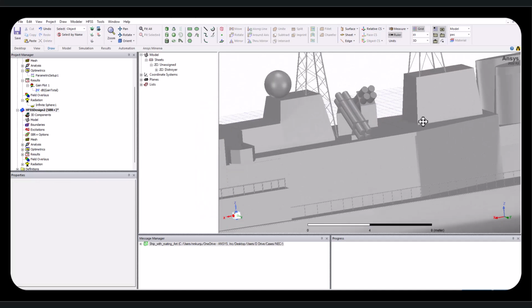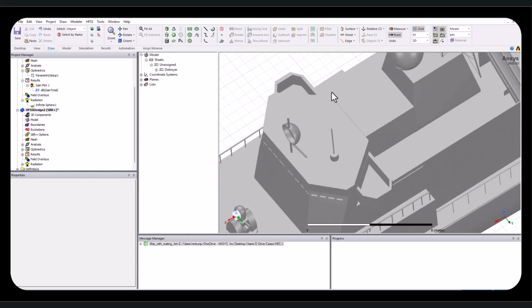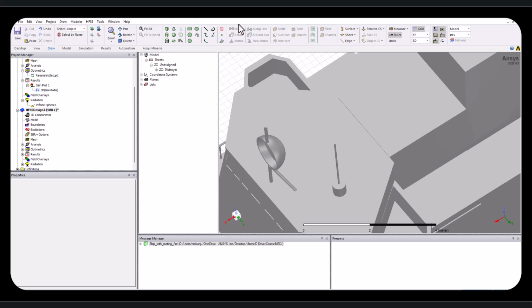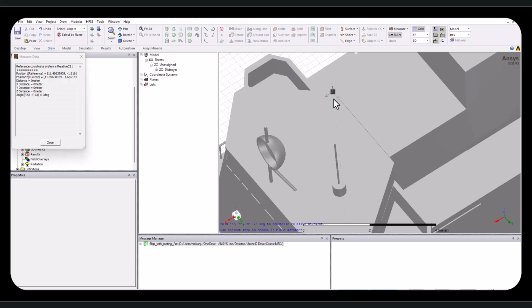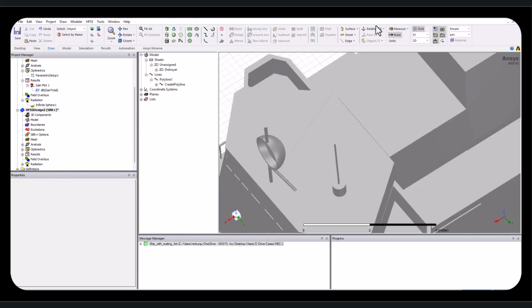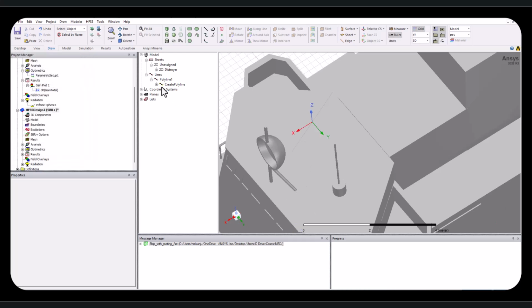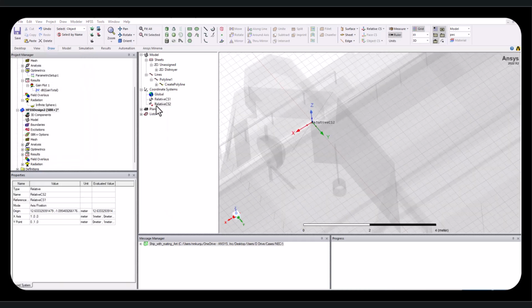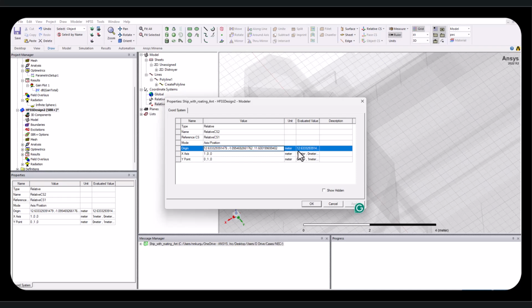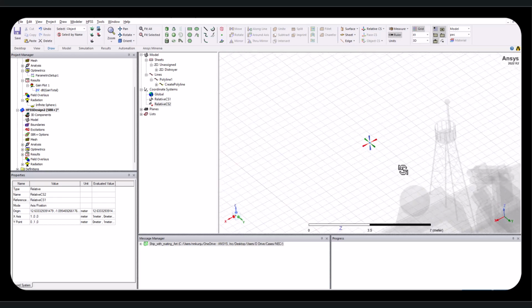Okay. And what I'm going to do is I want to keep my antenna somewhere here. I will create a small line which will pick somewhere here. And I wanted to keep my antenna just somewhere here at some certain height. So keep this, automatically pick the center of that line and say move that coordinate by some distance, let's say 0.5 meter. Now I have this antenna.